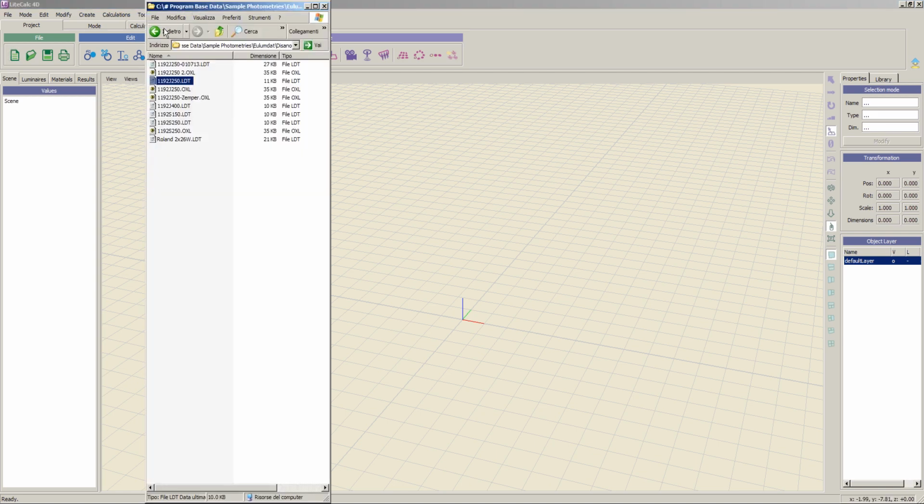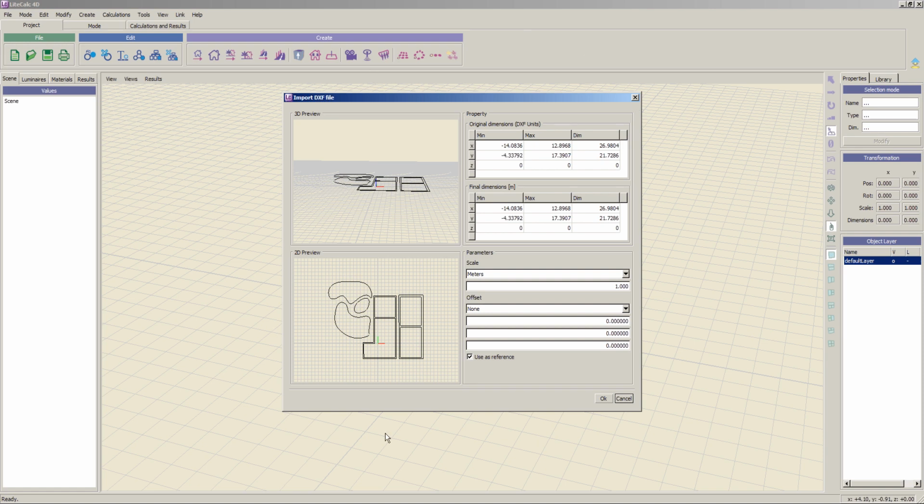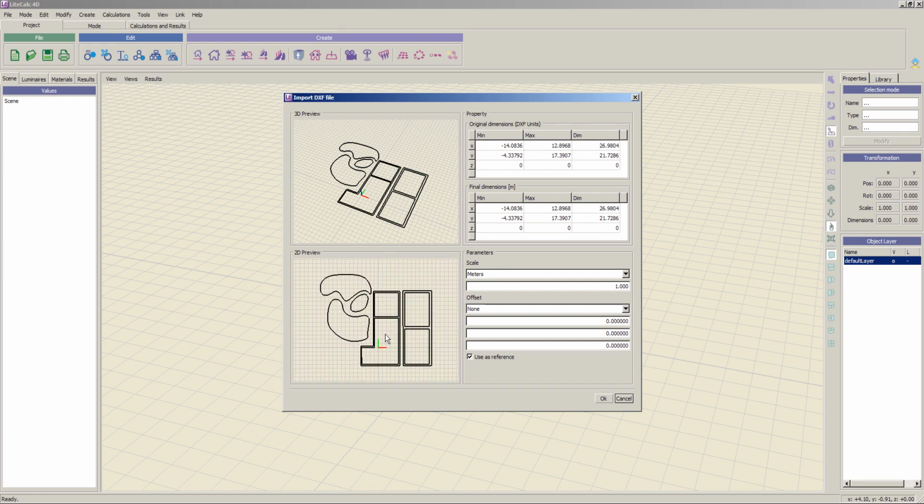We open, as before, an external folder. We select this area, and we simply drag and drop it into the working plane. This window will filter the DXF file and will show you what I described to you through the presentation. So in here I can zoom, I can rotate in a 3D view, perspective view. In here we have the top view, and as you can see in this drawing, the origin is placed not exactly in the center of the drawing, but inside the drawing.